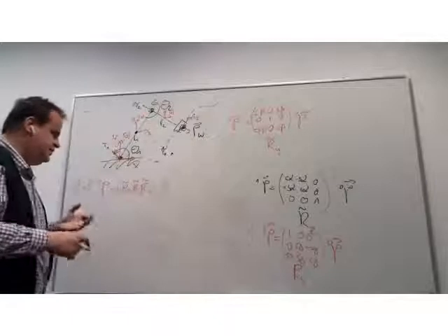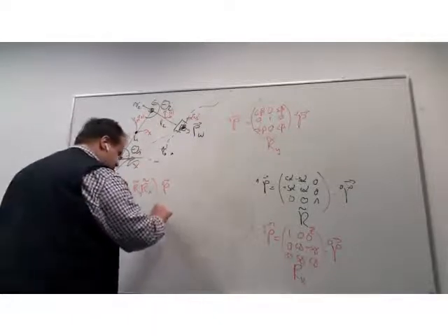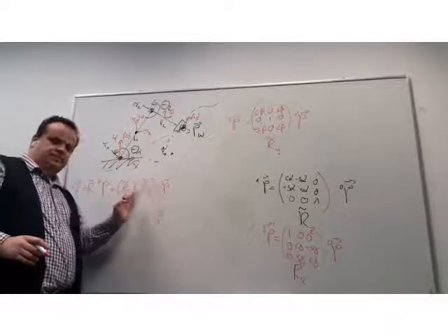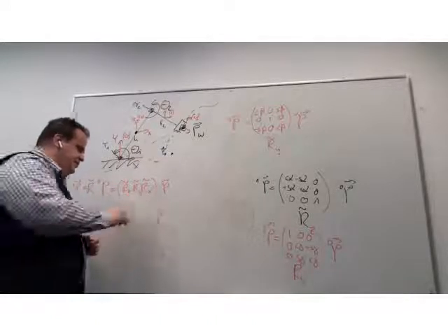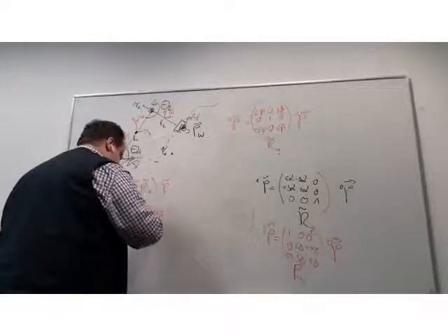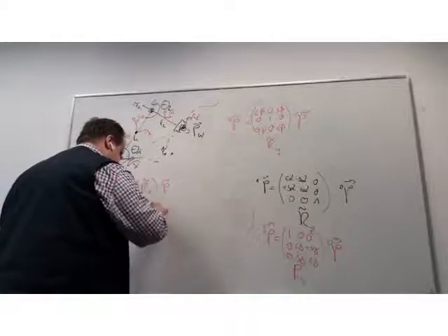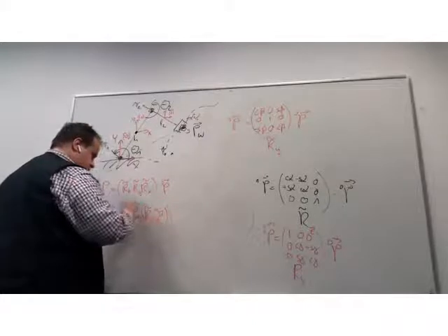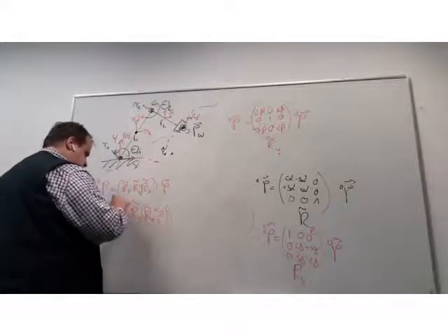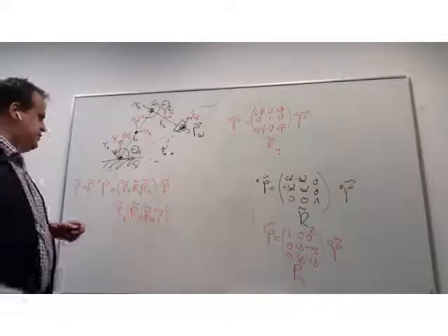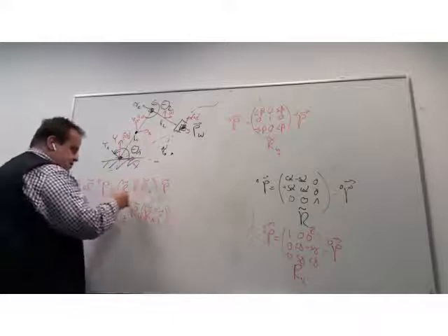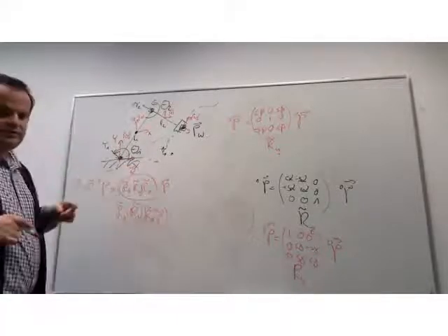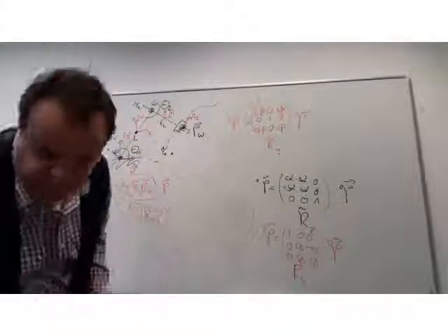You could understand it as first, the matrix operation will be applied on the vector from the left. So first we would do rotation around x. Then we will apply rotation around y. And then we will apply a rotation around z. So that means this product here corresponds to the rotation matrix R.